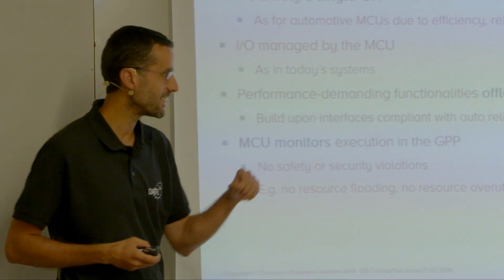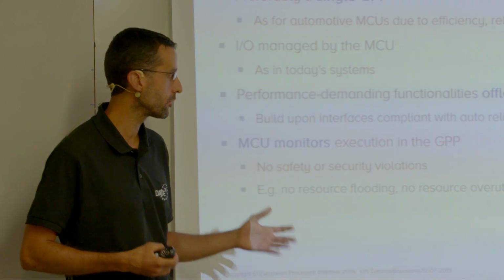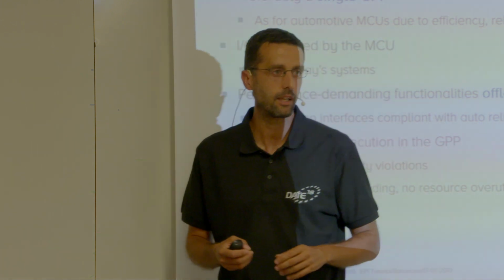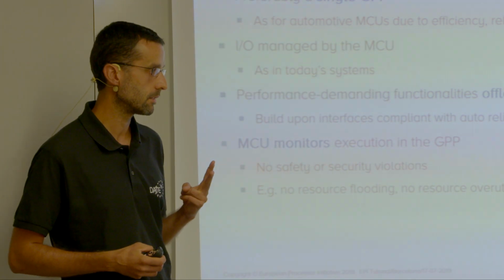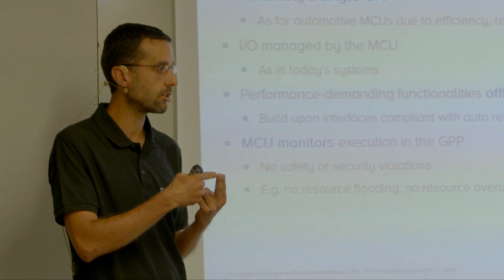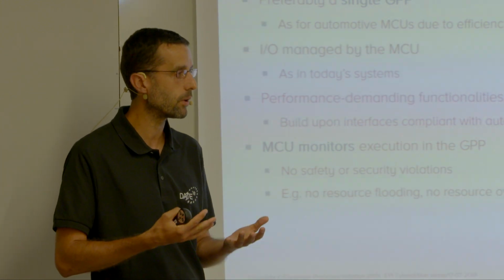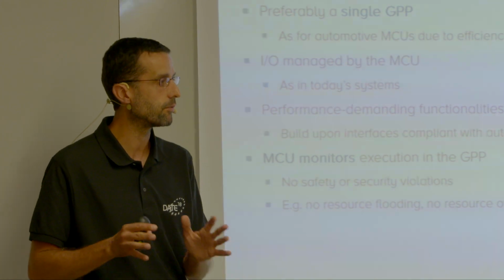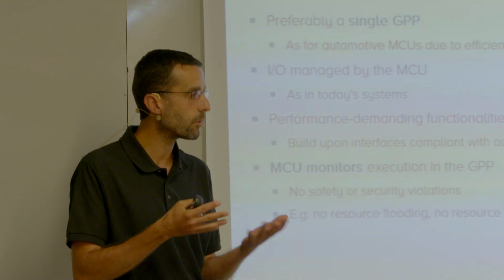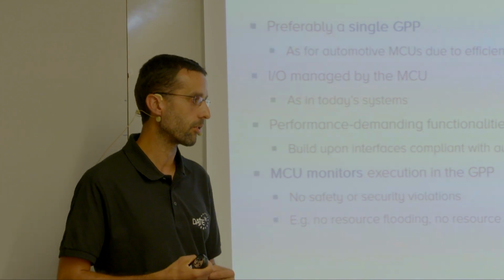No. I mean, this is already, let's say, a problem that is, I would say, solved in the automotive domain because when they work only with this microcontroller, they typically replicate functions twice for efficiency. What they do is that upon a mismatch, they reset and re-execute. Because by construction, these systems are verified in a way that you can guarantee that they lack systematic faults. So faults that may appear are random. So they are mostly guaranteed that by resetting and re-executing, execution will be correct.